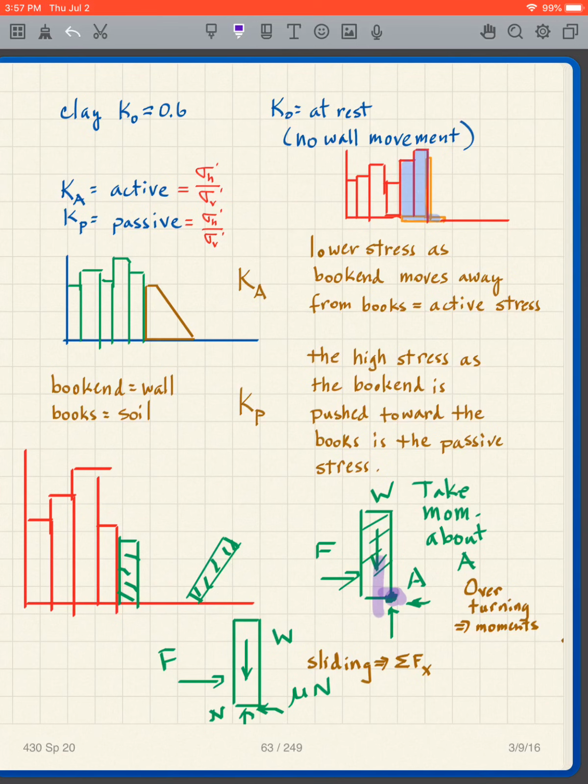So I need a wide base with the idea that I make my moment arm much larger, and so I can generate the resisting moment due to the weight. I get a much greater resisting moment, caused by the weight, because I have a much greater moment arm. So I need that wide base to prevent overturning. And then, of course, I need the weight.